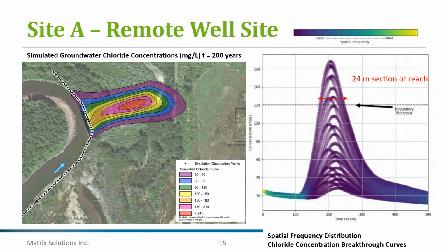So a numerical model of groundwater flow and chloride transport was constructed and calibrated for the site. The 3D chloride distribution that we developed was used as the initial condition for the transport simulation. And for the groundwater flow direction, again, we just assumed constant flow to the west towards the river.